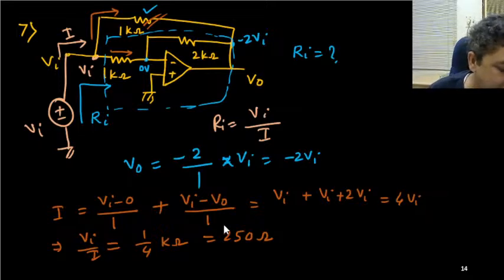For unity step input, the differentiator will be unstable. So you are giving these things practically. If it is a step signal, at that moment only it will be a spike and then it will be zero again. So one spike will be there at zero time, and then again it will become zero.